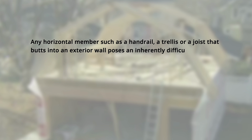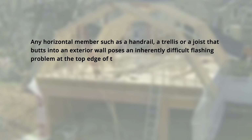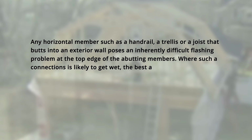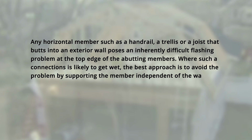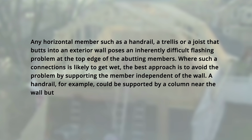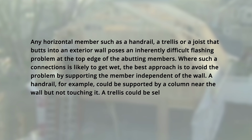Flashing. Any horizontal member, such as a handrail, a trellis, or a joist that butts into an exterior wall, poses an inherently difficult flashing problem at the top edge of the abutting members. Where such a connection is likely to get wet, the best approach is to avoid the problem by supporting the member independently of the wall. A handrail, for example, could be supported by a column near the wall but not touching it. A trellis could be self-supported.